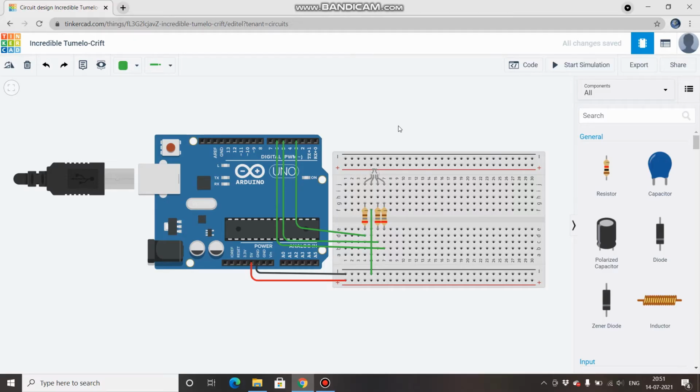This is the circuit for using RGB LED with Arduino. The common cathode terminal has been connected to ground and these 3 R, B and G terminals have been connected to respective PWM pins on Arduino. Now you have to be careful while using RGB with Arduino. You have to always connect PWM pins to R, G and B respectively.